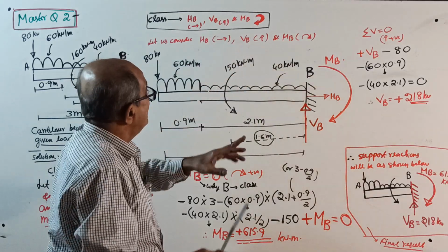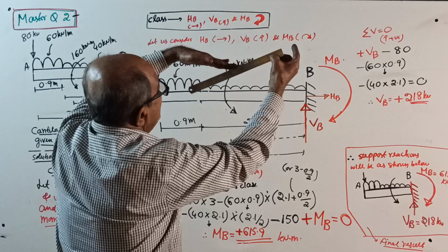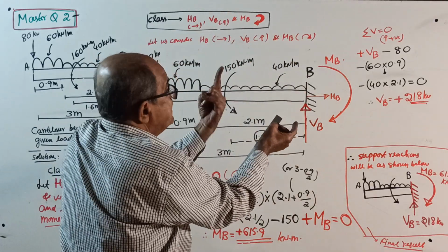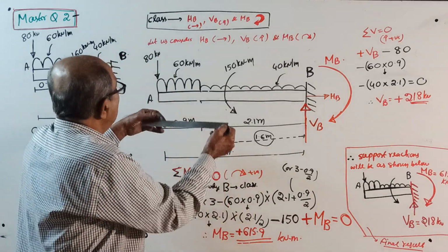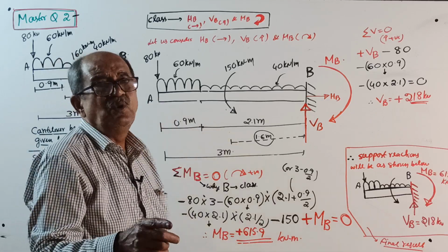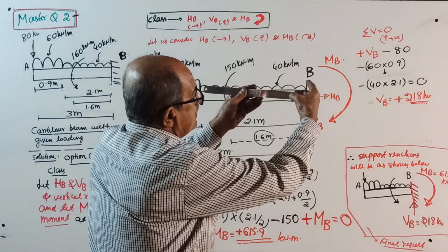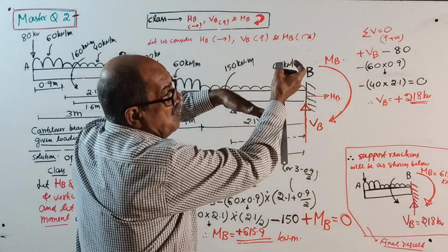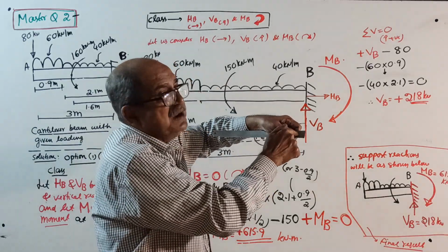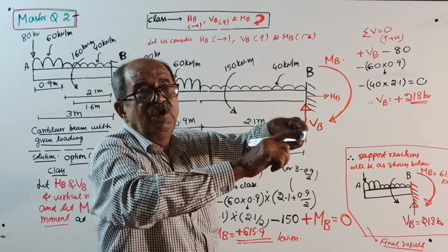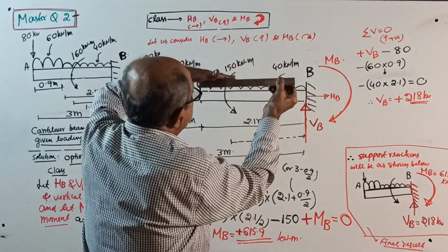See, this time, right here, you should write: this time, the fixed support is at B. See here, the loading on the beam will try to rotate the beam in the anti-clockwise direction with respect to, where is your finger? With respect to means, where is your finger? If I hold the finger here, the load will rotate this way, but this is not the point. I told you where the support is. Reaction comes in the support, not the free end. So if you put your finger at the fixed support on the right side here, the loading will try to rotate the beam in the anti-clockwise direction with respect to the fixed support at B. That's why your finger is at B. Therefore, for equilibrium, that is action, the fixed support will give a reacting moment in the opposite direction. Since the load rotates this way, the reaction will go this way.